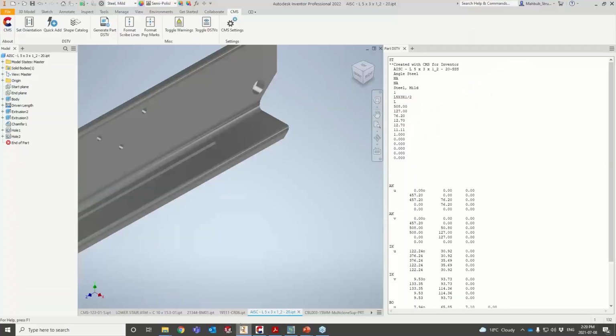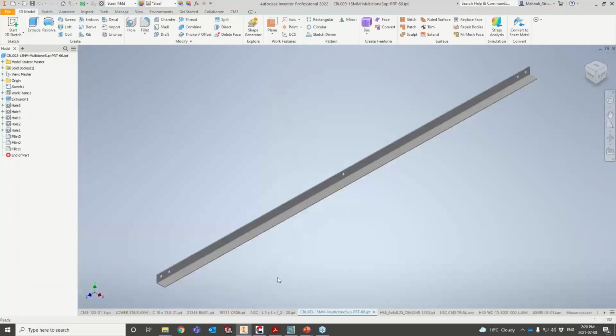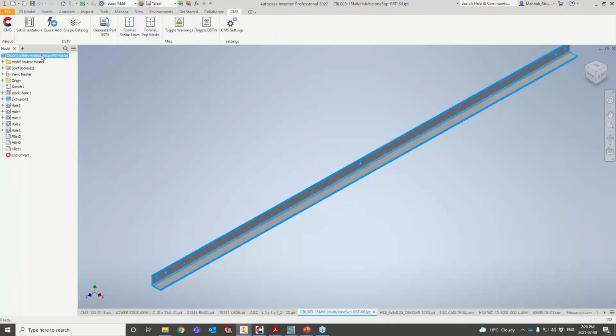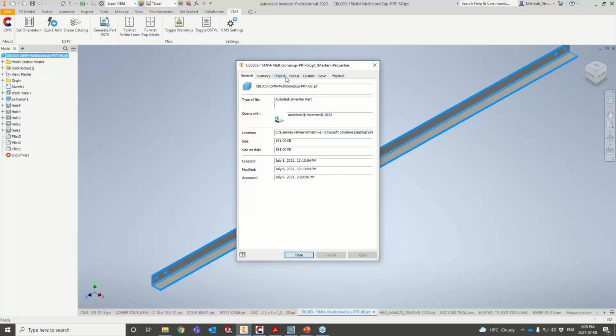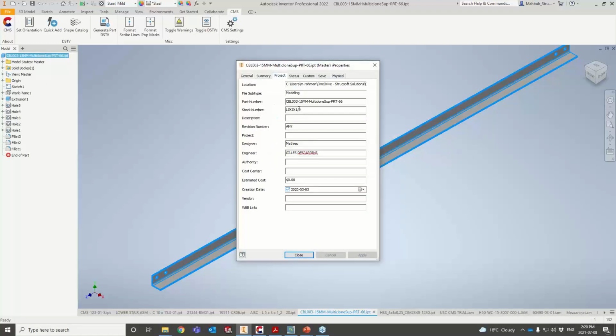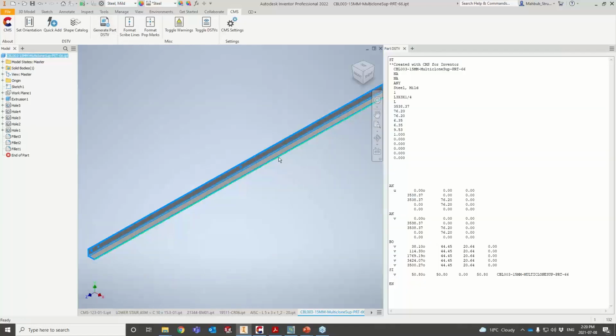So going back to my other examples here. The drill is the same for your angles with drills, in equal angle. We'll grab your size information, as I said before, from your stock number. It could be anywhere, not necessarily stock number. I am following stock number, so it could be in your description or in your material, whatever you want. So same drill, create the NC1 file from there.